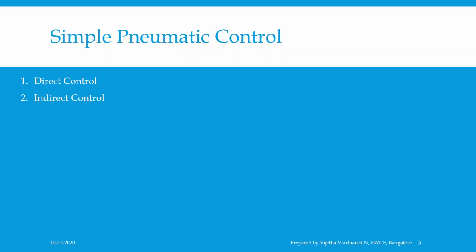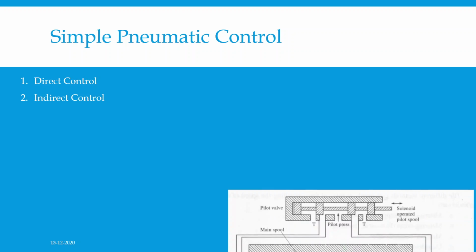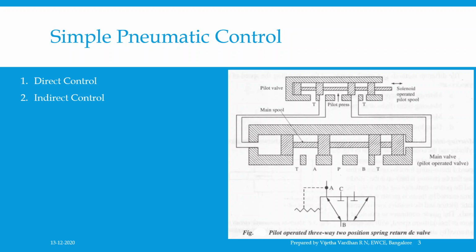In some cases, a control valve requires large force to actuate the valving element. Application of such large force will be difficult even in manually actuated valves. In such cases, another valve exclusively for actuating the control valve is used. Such a valve is called a pilot operated valve. Now let us discuss the pilot operated valves. They operate at much lower pressure and hence require less force to actuate. The pressure at which the pilot valve operates is called pilot pressure.